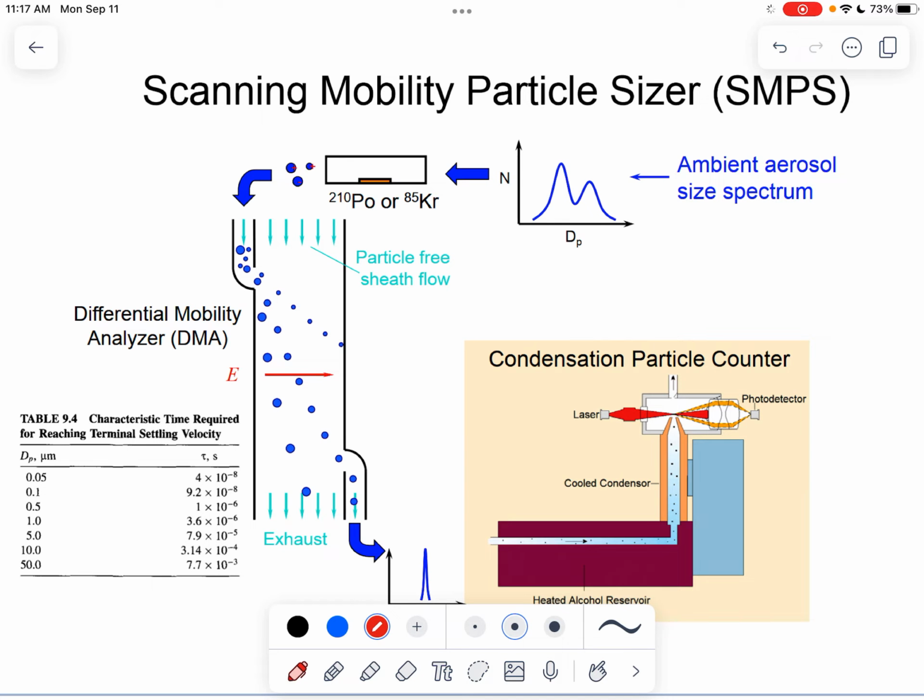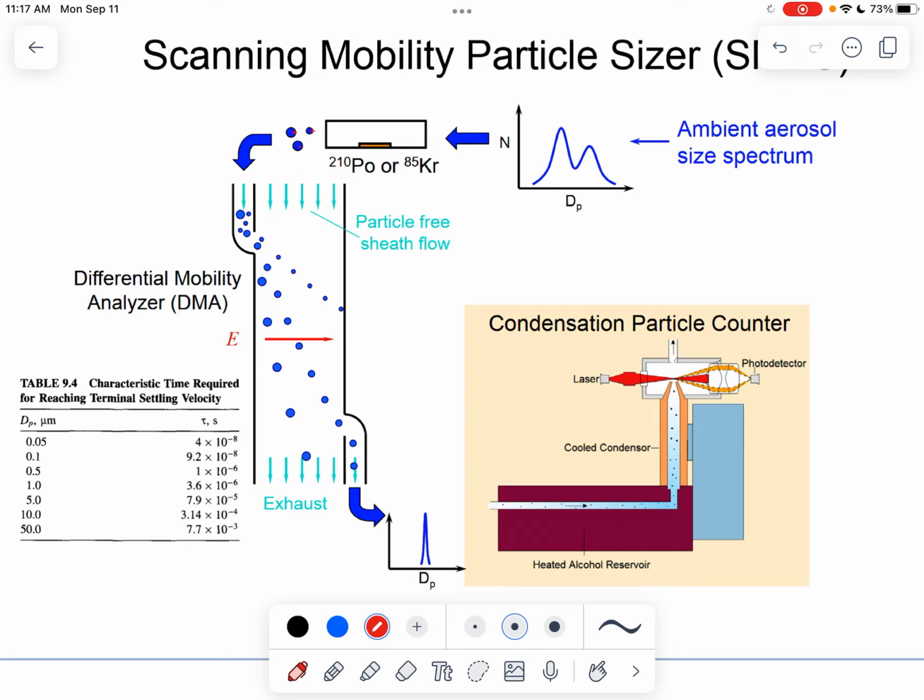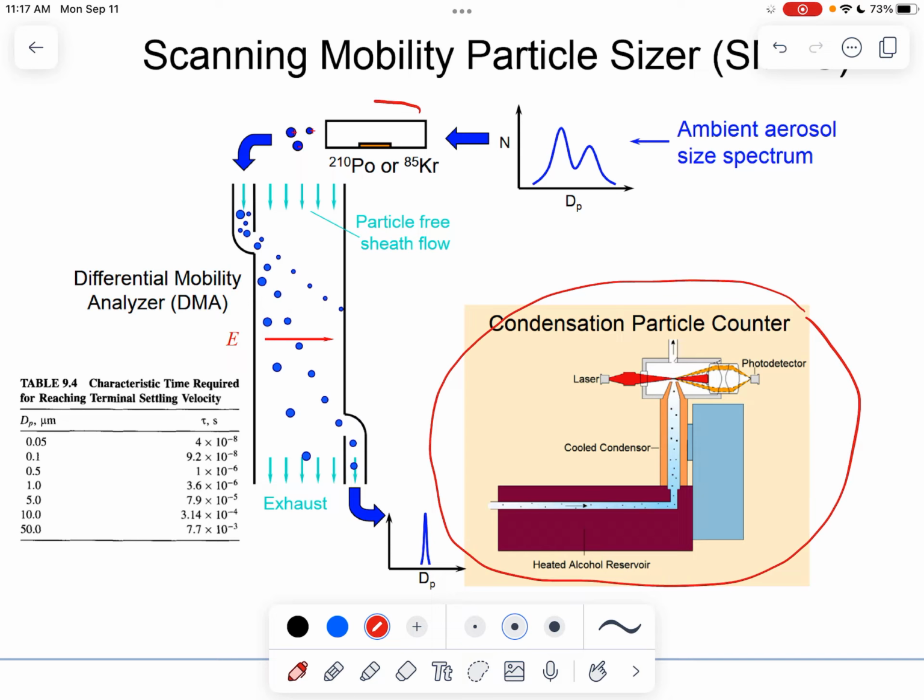Okay, so if we just go through this SMPS working diagram again, we can have a stream of the ambient aerosols being withdrawn by the SMPS. We said that eventually it's a CPC that's withdrawing the flow, right? So it's being withdrawn into the SMPS, and then we will introduce them into a charge neutralizer. So I would say for most of the current SMPS systems that we use, we normally will use these radioactive neutralizers.